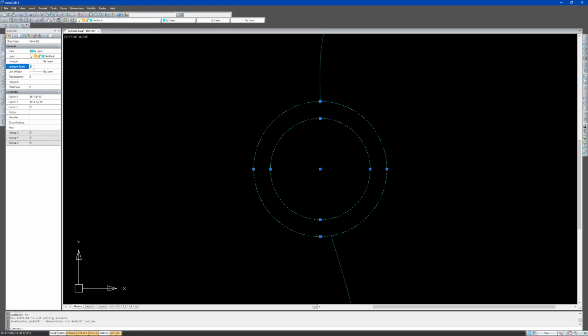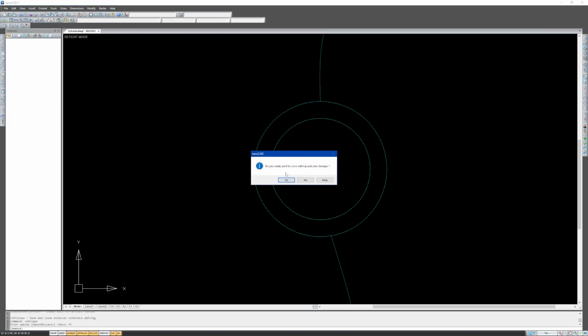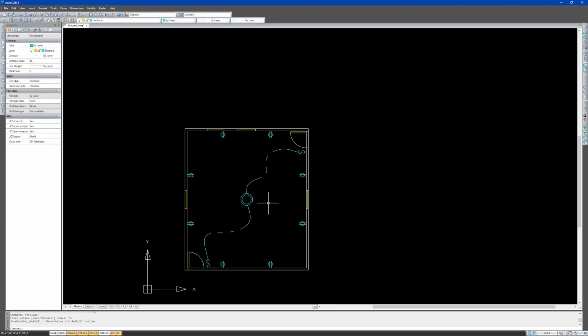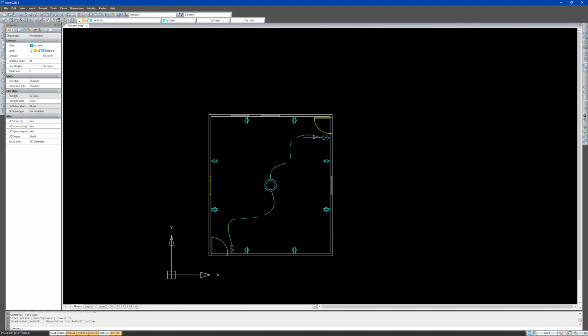So again, what I did, I double clicked the block. I specified this block to edit. I selected the lines, and now I'm changing the line type scale. And really, if you wanted to change the block while you're in here, you could do that as well. So for now, I'm just going to change the line type scale. Again, the scale becomes so big that the lines are essentially solid, which is fine. Really want to close? Yes, I do. And there you go. Now we have our electrical plan. We have a light fixture with 3-way switches and a few outlets throughout the shack.